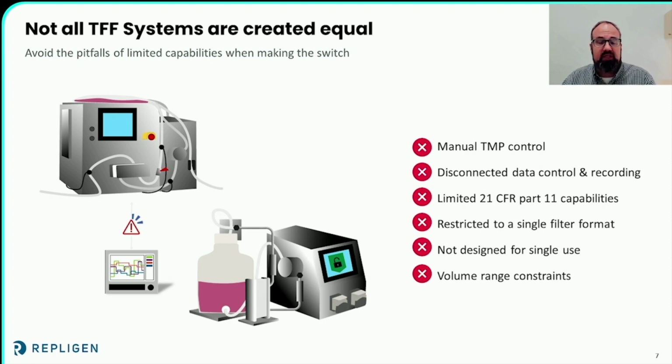At some point, you need to take this process to the next level, and you need a system that will allow you to get there. Many times the system design was geared towards the manufacturer's offerings for filter options and not agnostic to both hollow fiber and flat sheet cassettes. Perhaps there just wasn't enough recipe flexibility and could only operate simple processes due to the lack of equipment capability, which still leaves you operating semi-manually.